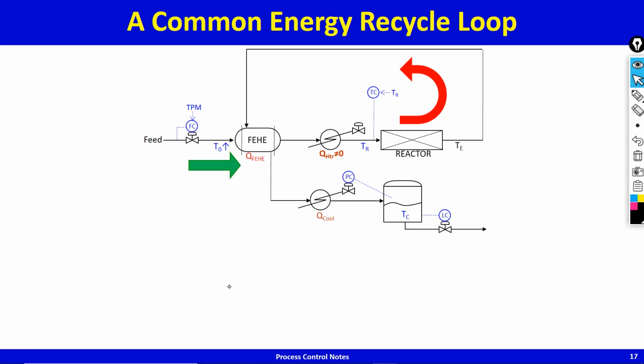So the nature of the process is, if the feed temperature increases, all temperatures in the recycle loop will increase a lot. Where will they settle at? They will settle at 100% conversion, whatever the temperature is corresponding to 100% conversion in the reactor. Yeah, because then you have no more fuel left to burn. Okay, but if you operate the process like this, all temperatures will go up.